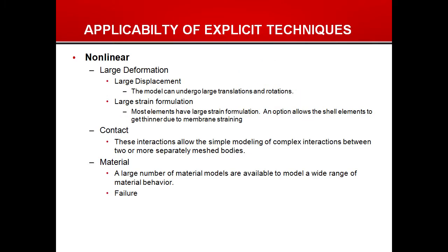Let's talk about nonlinearity briefly. Just like with the implicit codes, we divide and categorize the nonlinearities into three categories. Large deformation. Now, large deformation includes not only large displacements and large rotations, it also includes large strain formulations. Most of our element technology has these large strain formulations because the very nature of these types of simulations tends to involve large strain. So we handle that. That's all part of the code, and there's no extra cost that goes along with that.